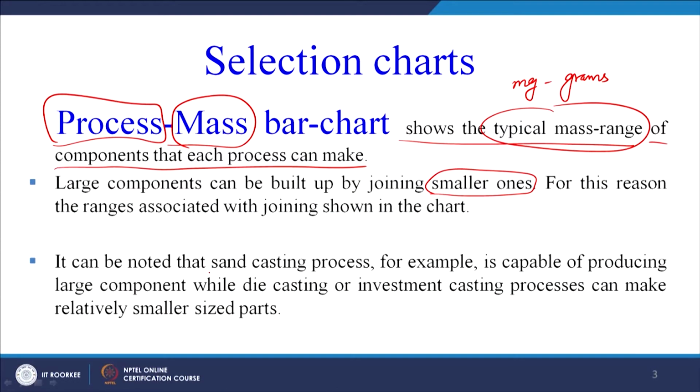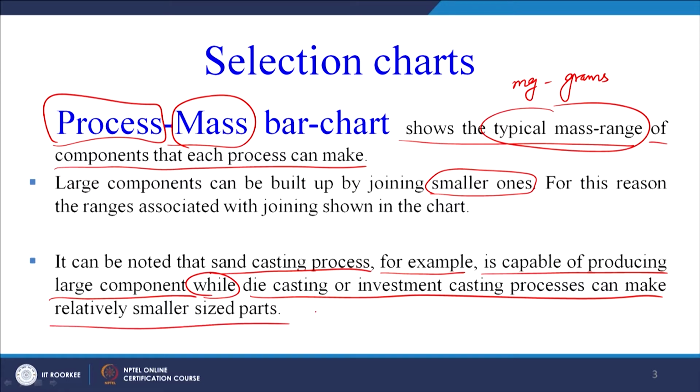It can be noted that sand casting process, which we have already seen, for example, is capable of producing large components, while die casting or investment casting processes can make relatively smaller sized parts. So as a product designer, such thumb rules must be known to us before we start our design process, that if the part size or the product size is large, or it is heavy, we can go for